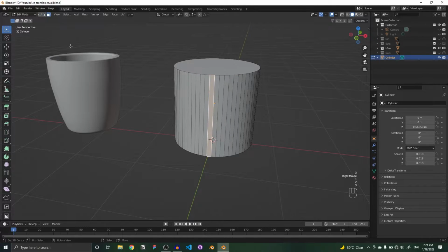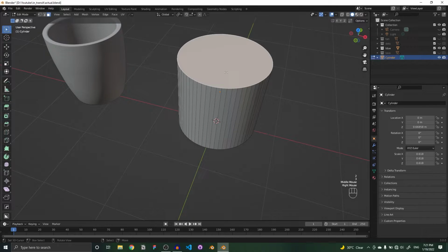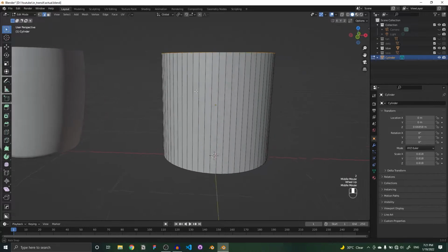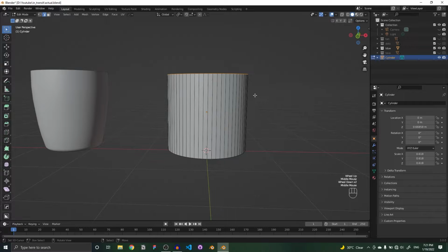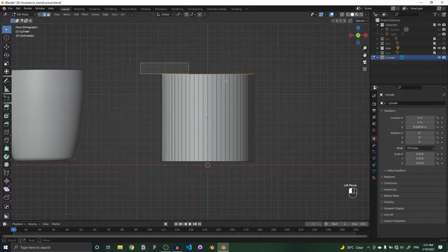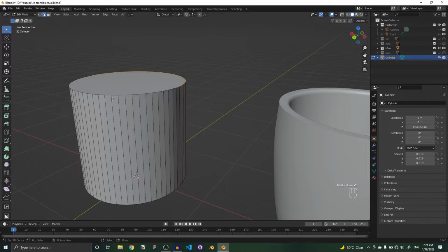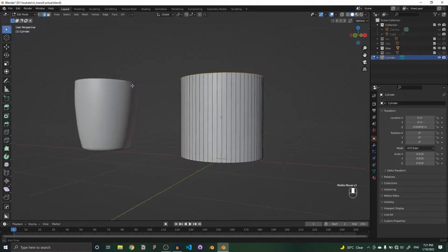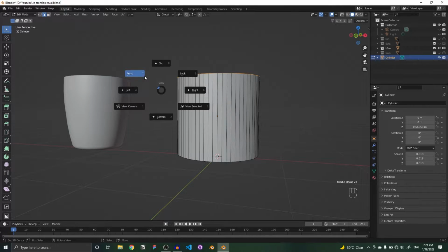So it's just the shortcuts. Now let's go to the edge select. Now when you're selecting the edges, let's click on the tilde button, the button beneath the escape key, and go to the front view. If you just select in this way, you click and drag, you will hope to be able to select the entire thing, but not. As you can see, this side of the viewport is not selected. So tilde key, front view.